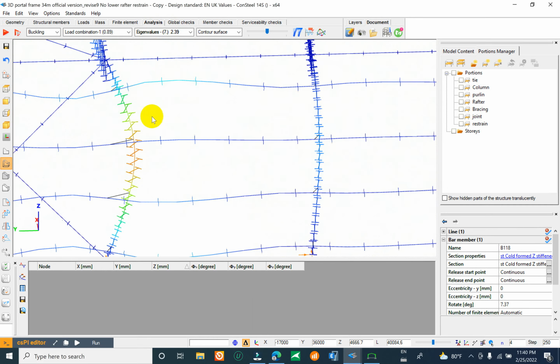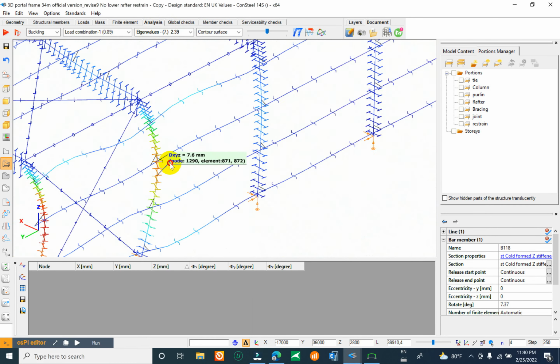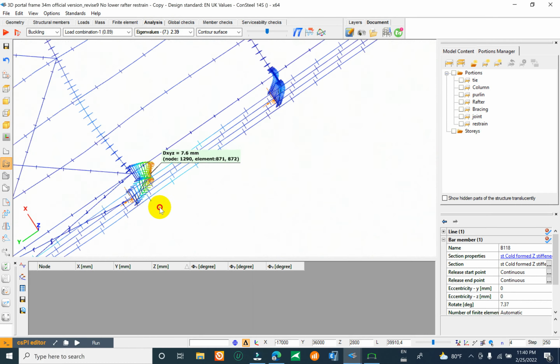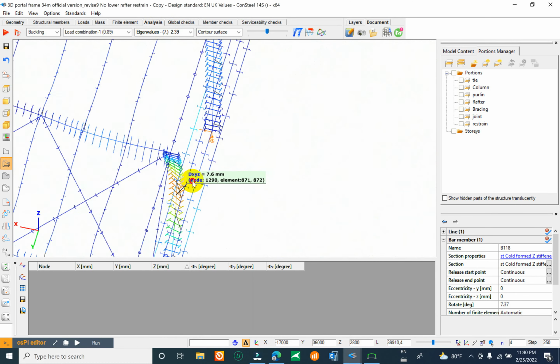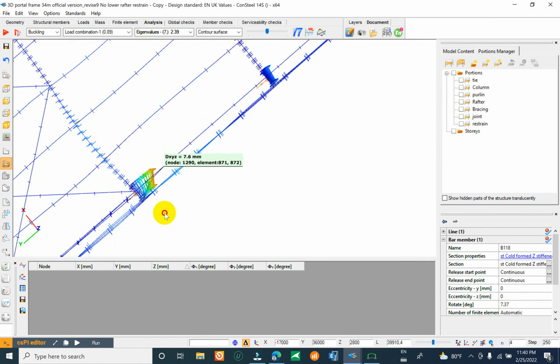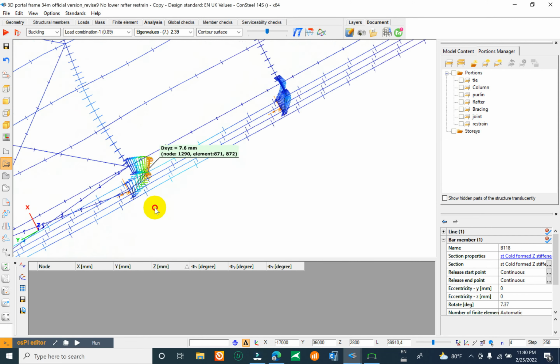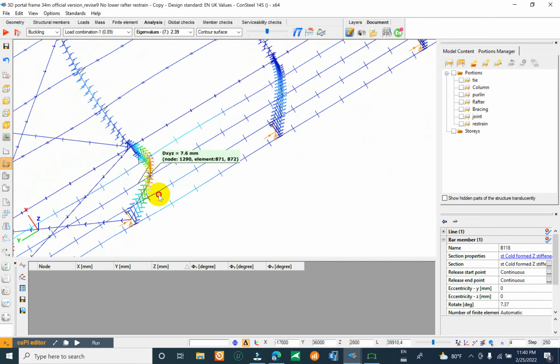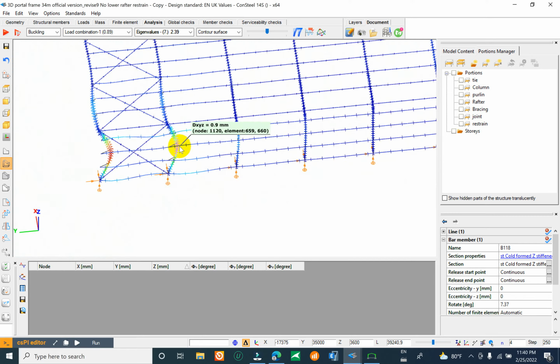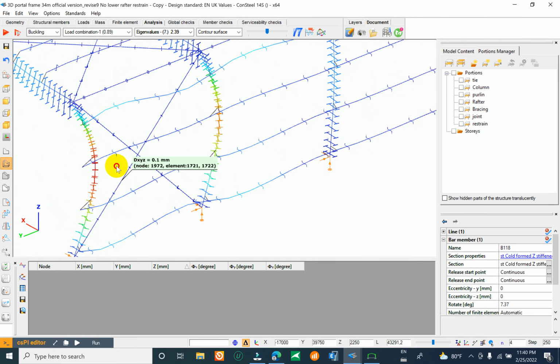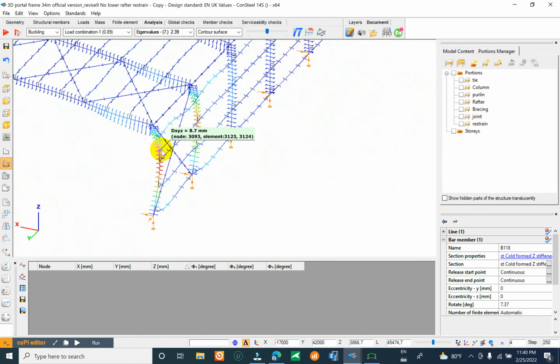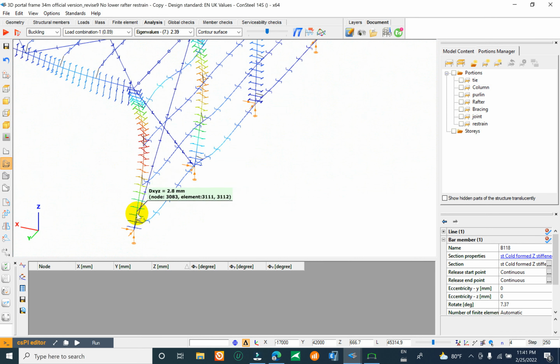You see your deformation also affected from the lateral and torsion. You can see here your section is twisted from the axis, okay. It is very important. You have to check the mode shape, and you know the shape of the structure effect, okay.